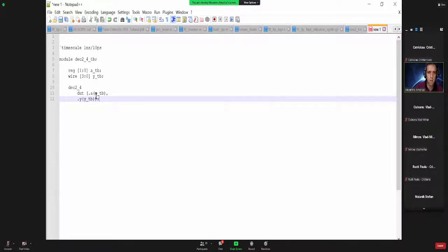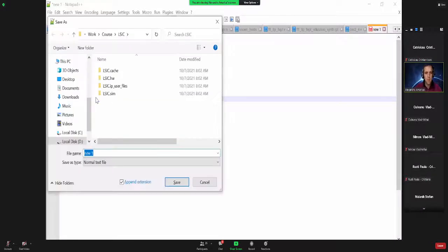Here you use the list of signals, on a position-based assignment. However, I usually have designs with something like 20 signals in the interface, so it's pretty easy to not match the position or to forget one. That's why I use this kind of instantiation.